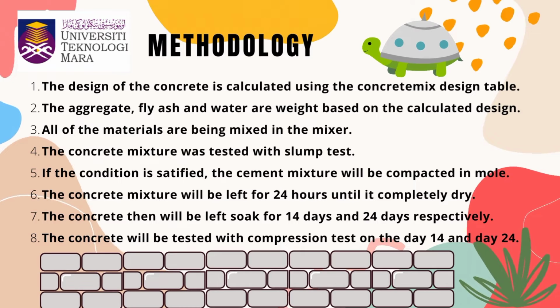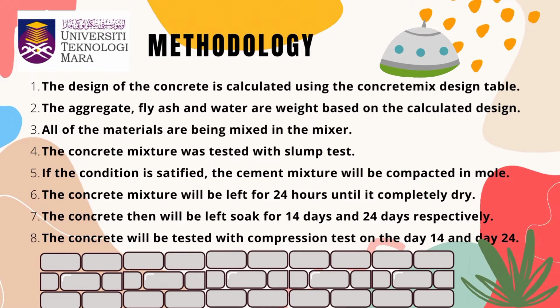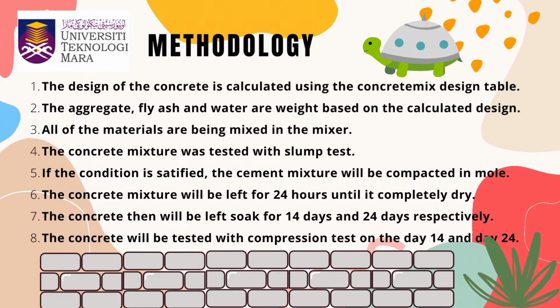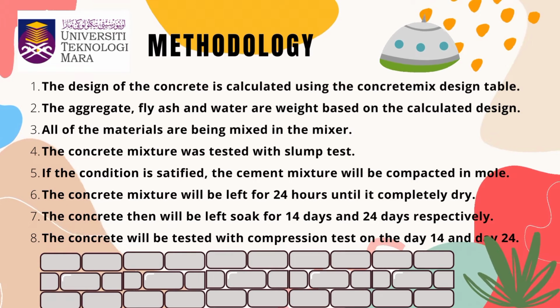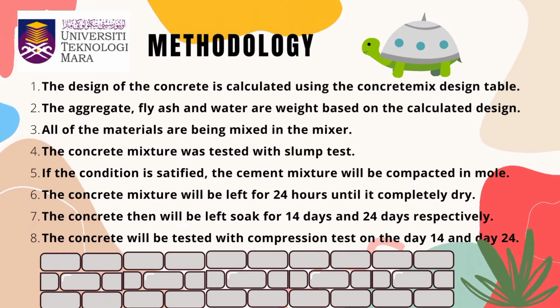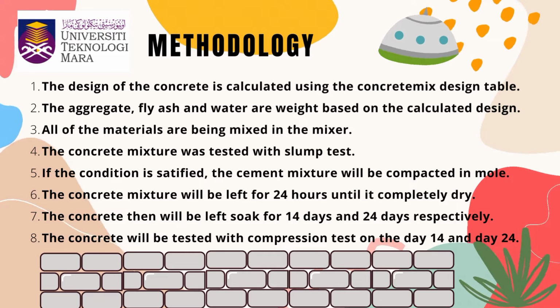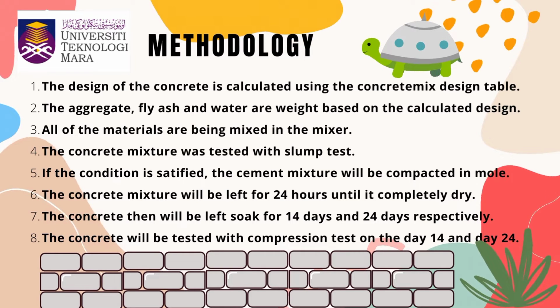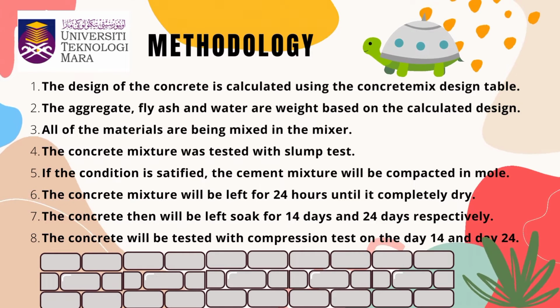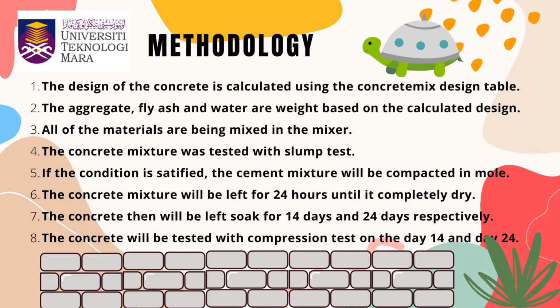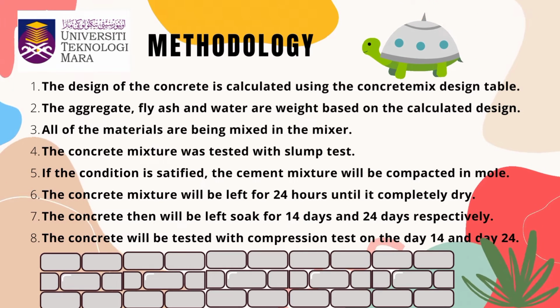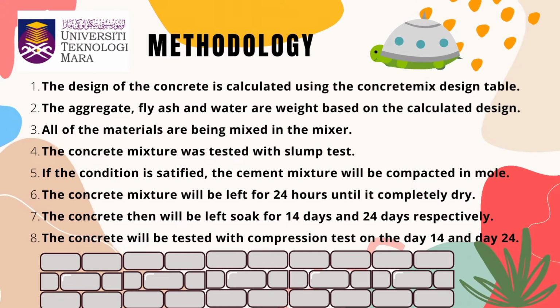The methodology started with the design of the concrete, which is calculated using the concrete mix design table. Second, the aggregate, fly ash, and water are weighed based on the calculated design. Third, all of the materials are mixed in the mixer. Fourth, the concrete mixture was tested with a slump test.